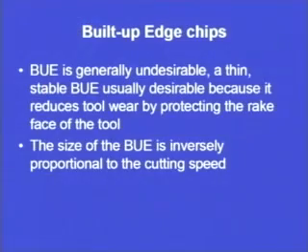Now, as we have seen, the built up edge alters the geometry of the tool and may result in rubbing action or may affect the surface finish of the final product. But built up edge is therefore generally undesirable. But a thin, stable built up edge means it should not be very thick, and it should not be unstable, it should be stable. We have seen that after some time it will become unstable and it will eventually break, and some part will be carried away by the chip, some part will be deposited on the workpiece surface randomly.